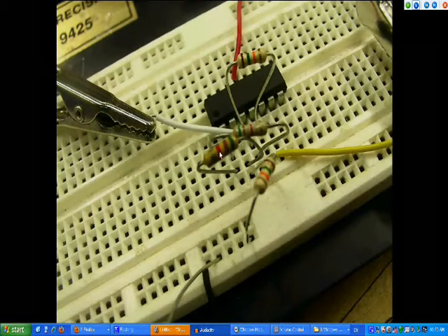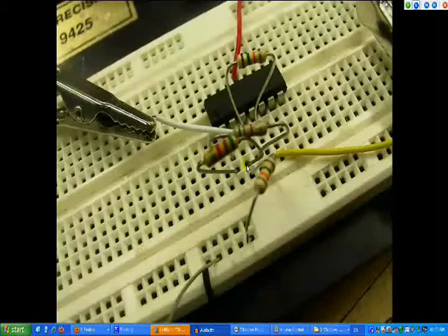And then we have a couple of 5K resistors. They both come out of the output here, as you can see. One of them goes from output to the inverting input, and one of them goes from output to non-inverting input. And then down here we have a variable resistor, which will vary from 3 to 12K, and see where the current, which should ideally be 1 milliamp, starts to drop off.